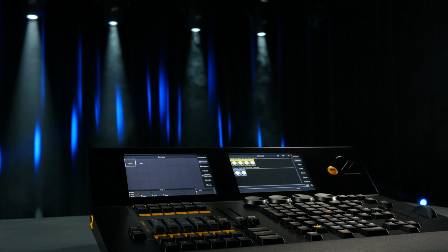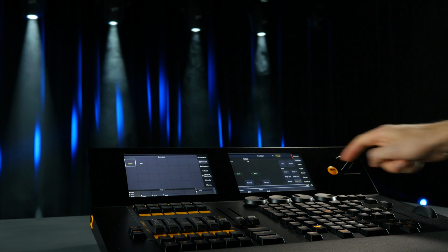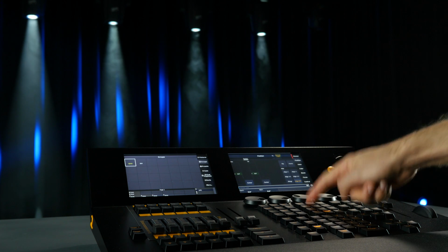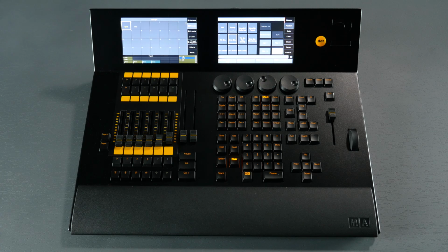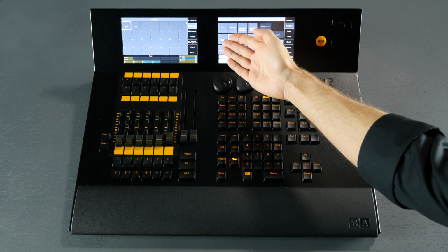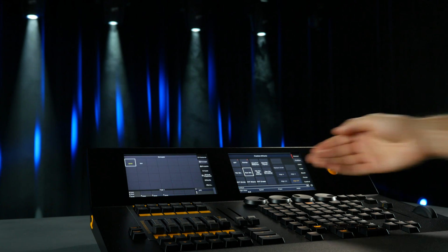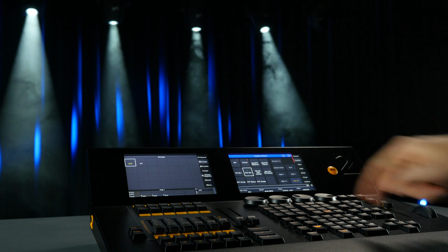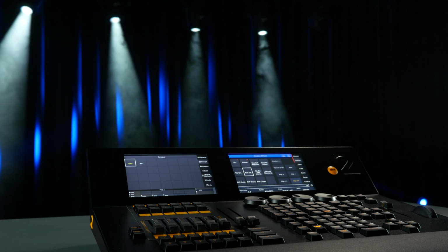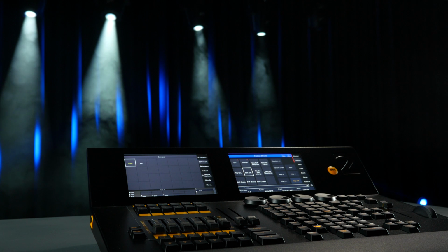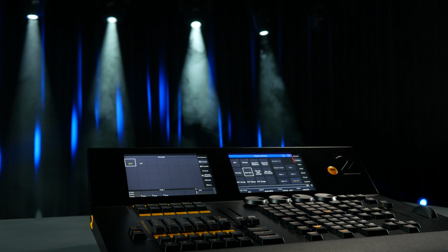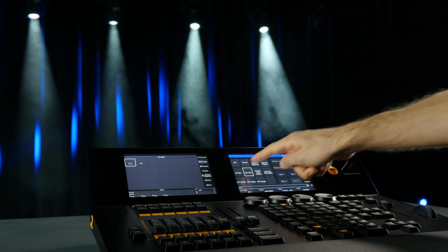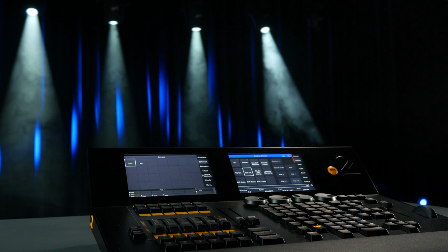We'll then select the position attribute from the buttons on the right side of the right screen and press the effects key to open the effect window. Here we have some effects for pan only, some just for tilt, and others that are combined. Let's see how this works by selecting the tilt sine and then pan sine effects. Now we can see both effects running. If we need to stop one of these effects from running, we just press the off hard key followed by the effect on the touchscreen we wish to stop.